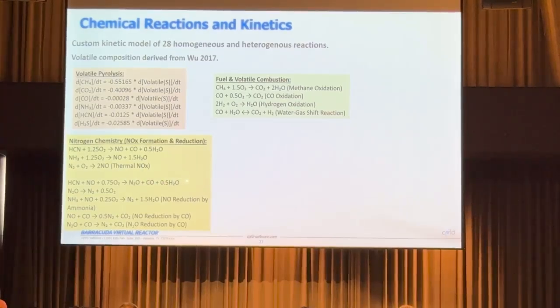So what you do is you actually run this case fuel rich, essentially, such that you can reduce your NOx emissions. Nevertheless, you do produce some NOx, and then the idea with this staged oxidizer index, secondary air index, is that you can reduce some of this NOx that is produced back into nitrogen or nitrous oxide and so on, right?